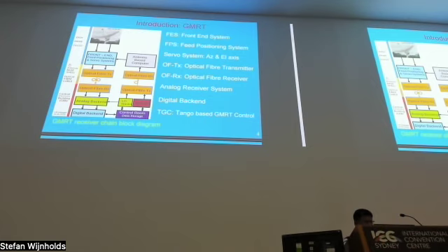Once the signal is received at the central electronics building, these light waves get converted again into electrical signals using photodiodes. Then the signal goes to the analog backend system, where signal conditioning and baseband conversion happen. Then the signal goes to the digital backend system for digital conversion, delay correction, FFT, and correlation.